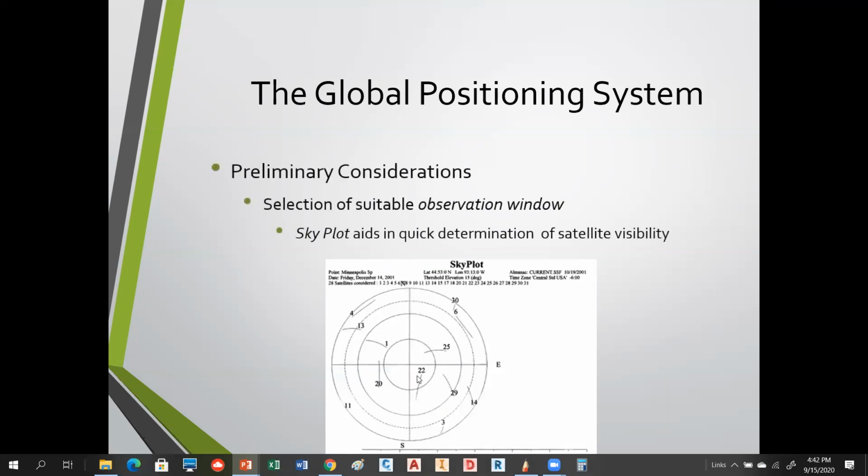From my experience, if you have satellites that are real low in the sky and they might be getting in the trees, or if it's just real low in the sky and there's interference off in the distance, sometimes just by increasing your mask or turning that satellite off, you can get a good solution. Yeah, you're saying basically it drives your PDOP low, right? Right. And one bad satellite can ruin the solution sometimes.